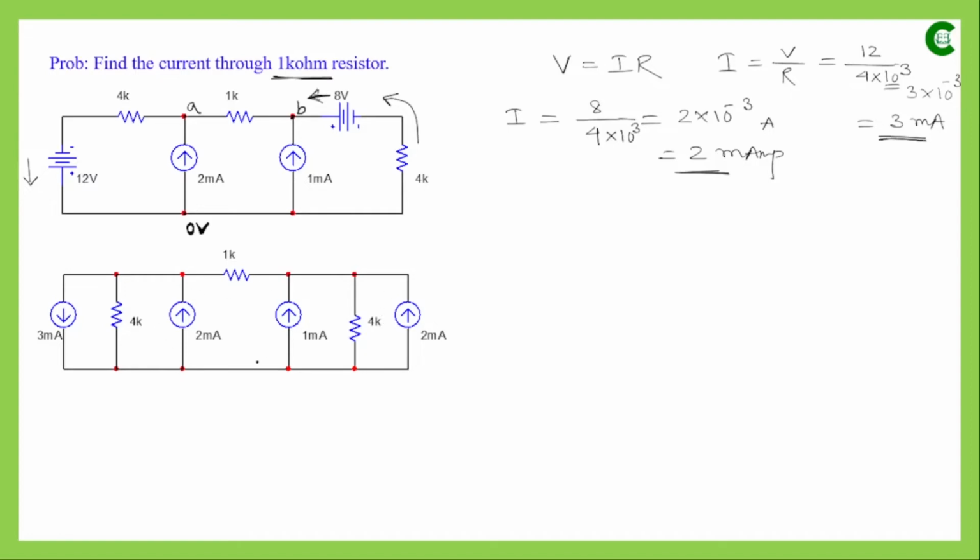Now in this circuit, as we can see, we have this node where these 4 components are connected, and at this node again these 4 components are connected, and at the node at the bottom we have 6 components connected. So all these 3 nodes are principal nodes. Now we will connect this node to the ground, and we will make this our reference node.